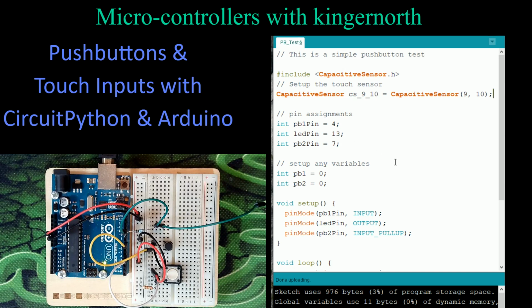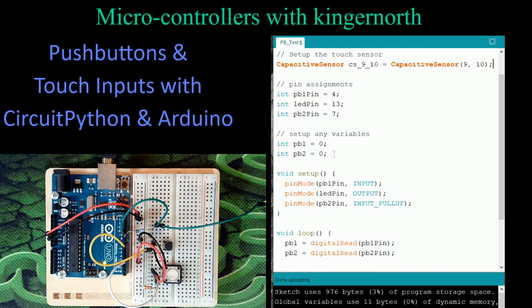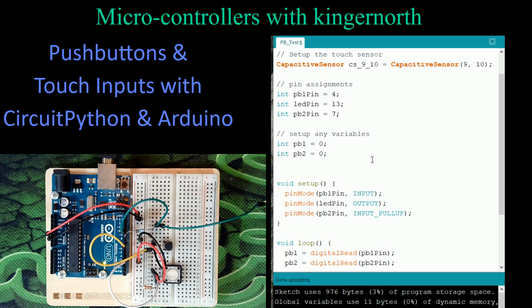So we're going to show a little bit more how this works, because this creates the actual assignment for this one. So that's our touch sensor. That takes care of the touch sensor. So now we're going to come down here. I'm going to create one new variable though. I'm going to create a Boolean value of true and false. So I'm going to call it Boolean, and I'm going to call it touch. And I'm going to start out with it equaling false. And by doing that, I'm just saying it's equal to 0 at this point. But this is just a Boolean.